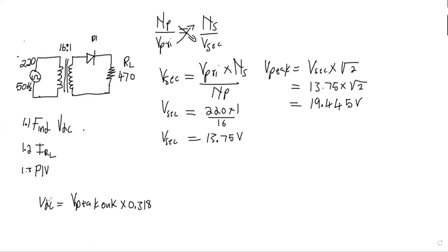That is the formula for VTC. So that means for us to get the VTC, we need what? V peak out. And to get the V peak out, we need the V peak. So V peak out is equal to V peak minus 0.7.